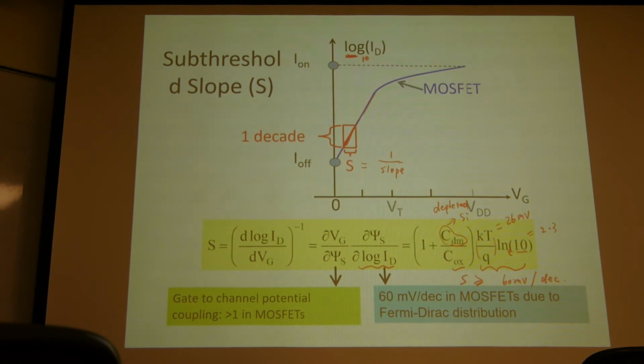So typically today's transistor, even for today's like 7 nanometer TSMC or 10 nanometer Intel transistors, the threshold voltage is still like 0.3 volts or 0.4 volts, 300 millivolts or 400 millivolts. You cannot reduce further. Why is that? Because of this S. Okay.